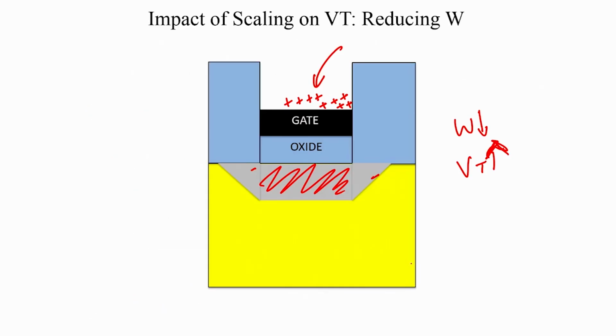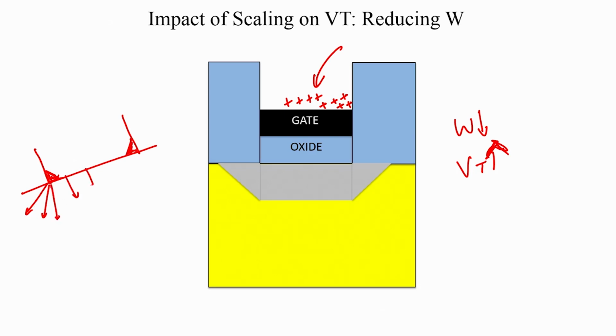And we are going to model this extra region not like these little triangles, but along these fringing lines, the fringing electric field. So it is going to have more of a circular profile, with these circular arcs. Although I have shown it with straight edges just because it is easier to draw, you have a gate, you have an insulator here, and if you look at the edge of this insulator, it is a sharp corner, and this corner is going to have a very strong fringing field. So that is the way the field lines are going to be present.